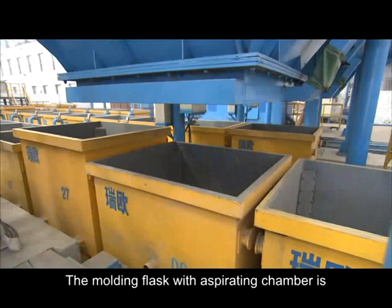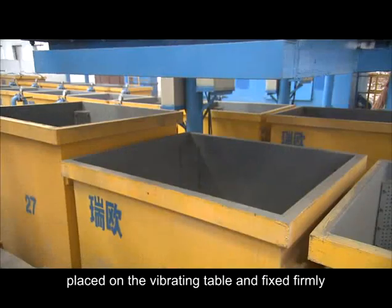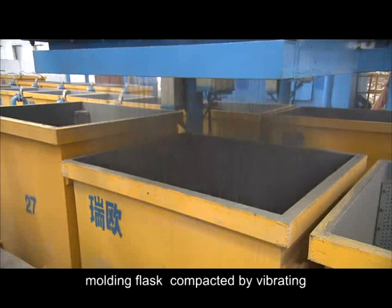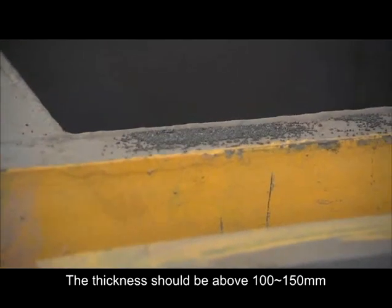Bottom sand. The molding flask with an aspirating chamber is placed on the vibrating table and fixed firmly. Some sand is filled in the bottom of the molding flask and compacted by vibrating. The thickness should be above 100 to 150 mm.